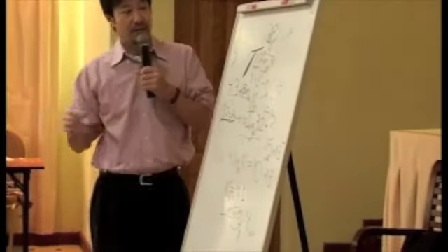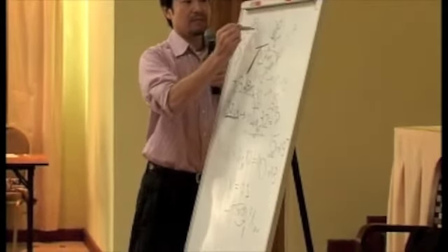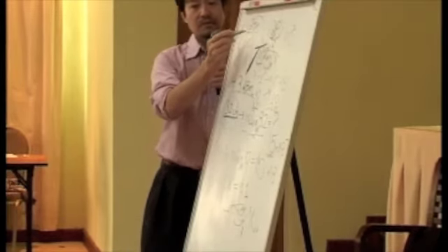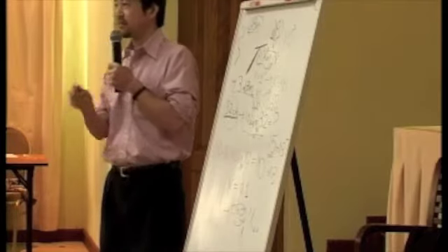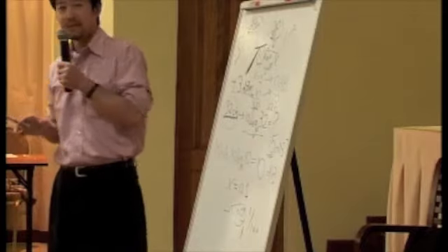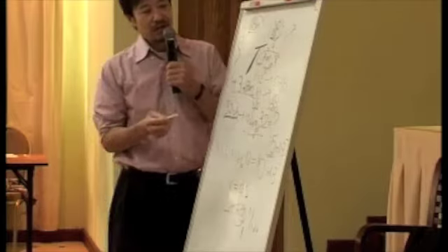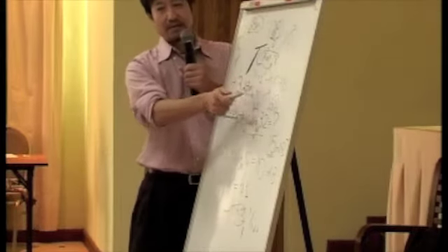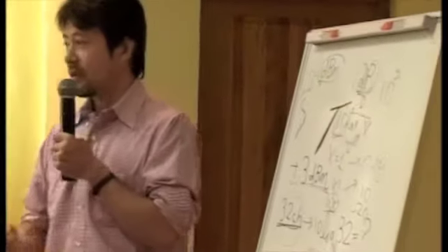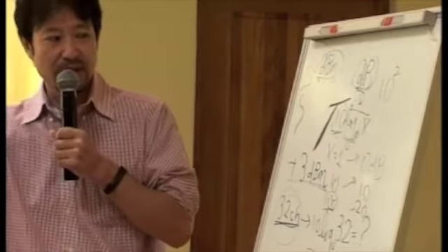So we often see the dB scale in this handbook. And next, we also see the unit dBm to express optical power. Do you know dBm? What's the difference between dBm and dB? dB means just the relative value of something, 10 times, 100 times, or 1,000 times. So 10 dB, 20 dB, 3 dB, we say.